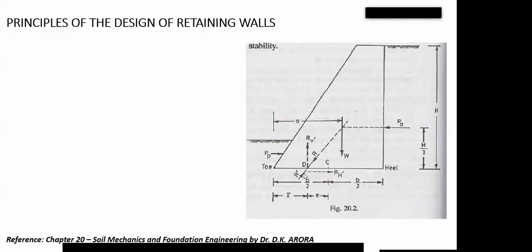Opposites. Now, also, I can resolve this into my vertical reaction and my horizontal reaction. So basically, you can resolve your weights into the vertical and horizontal aspects. Your weight and your lateral edge pressure are given in the vertical and horizontal aspects. Your lateral edge pressure is the horizontal, your weight is the vertical. Now you can generate a resultant of that.